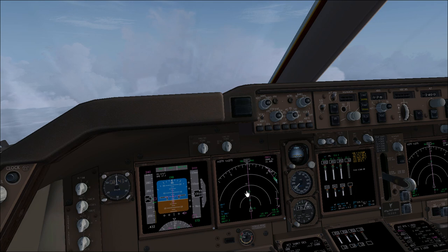Those 2 points are actually the speed down points for flight level 100. The first one is when the FMC commands 240 knots. The second one is when you reach 240 knots. In this case, we are flying at flight level 140, so this distance is standard. It's not calculated directly from the FMS, but is just showing a standard possible altitude.